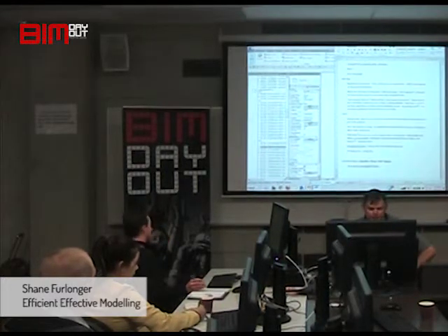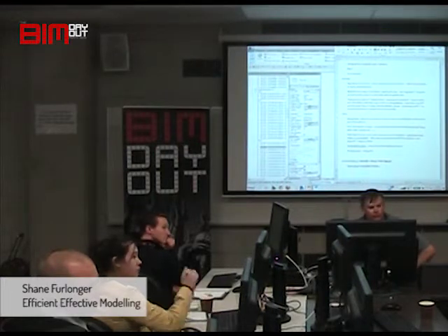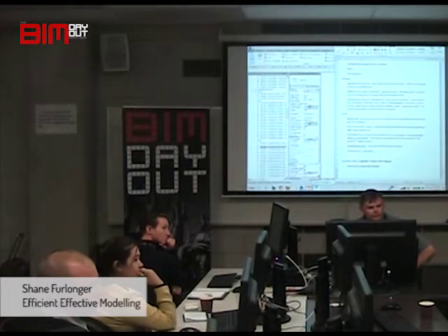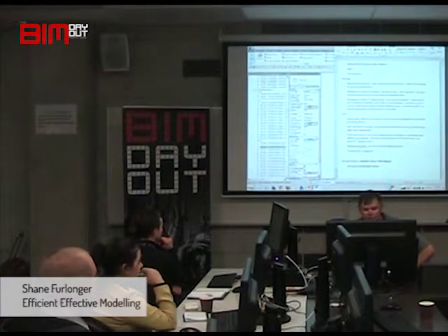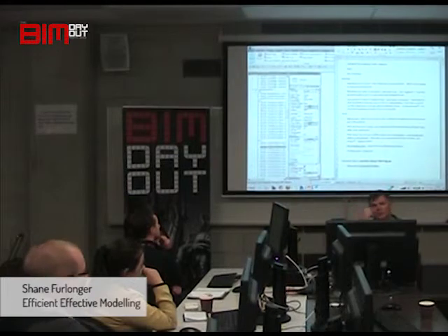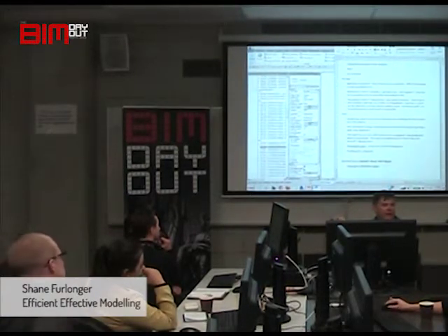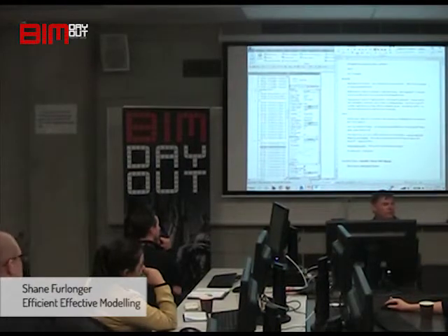Where are we? Ceilings as well should be off the ground area, because then when you go to tag it, it's like a certain amount above full level. Yeah. Let's say if you align the ceiling to a ceiling level and you tag it, then it's going to be 0. Mm-hmm. Now, another thing with ceilings is you may have noticed you've created a room, you've put in a ceiling, and you want to move the wall. And the ceiling moves with it.